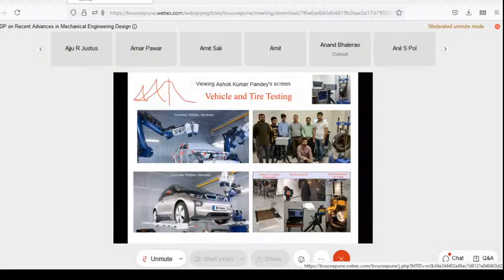The first purpose, whenever we design a vehicle, is to really know what the frequency of that is. Okay, so as I said, one way is contact based measurement using accelerometers, and another method is laser based non-destructive measurement. Here you can see the scanning laser vibrometer from Polytec. It generally has these heads, called scanning heads. With the help of these three heads, you can do 3D measurement of any kind of structure. If you have one set from here and another set from here, you can scan it everywhere, and then you can have the complete vehicle testing solution altogether.